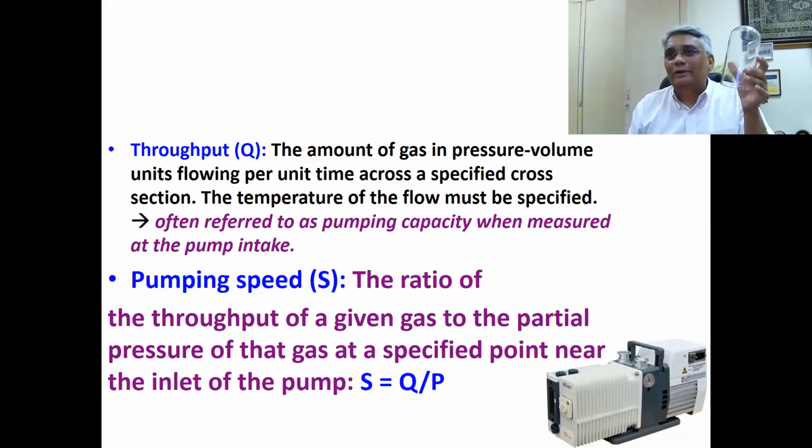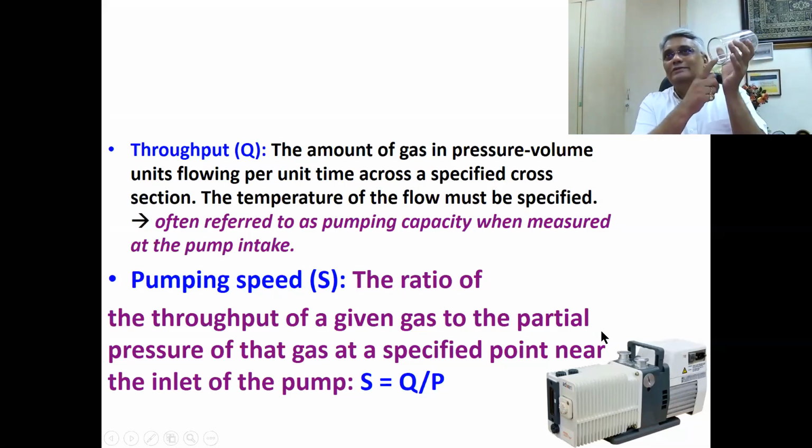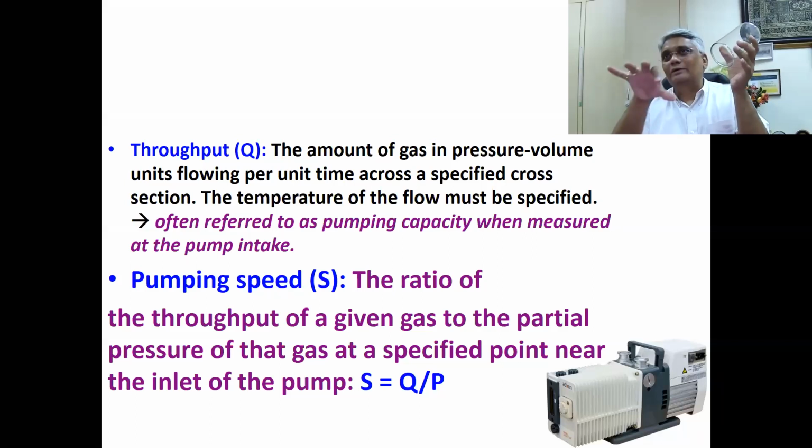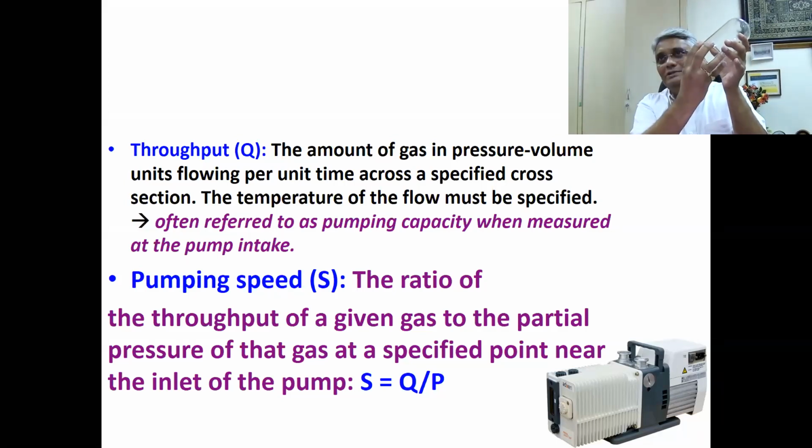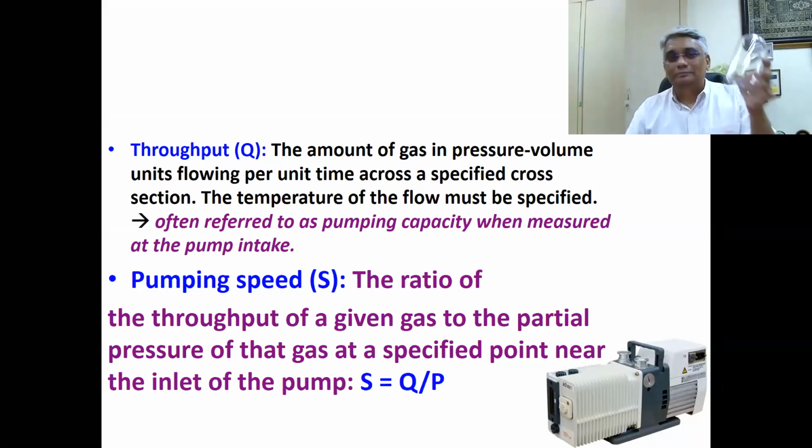But this cannot happen. You can look at the size of the inlet there. It's about 1 inch, and the size of this opening here. So you cannot connect here. You need to have connectors. I need to have a connector that couples here, and then the pipe has a reduced dimension which connects to the other side of the pump.